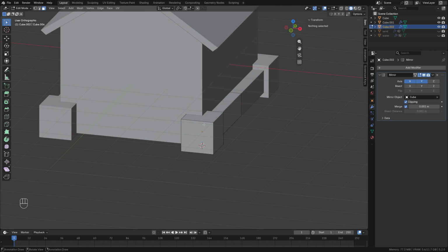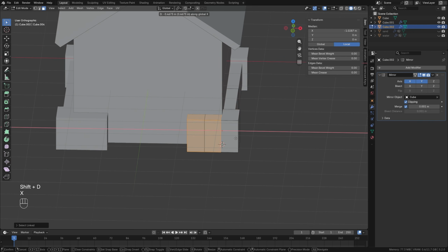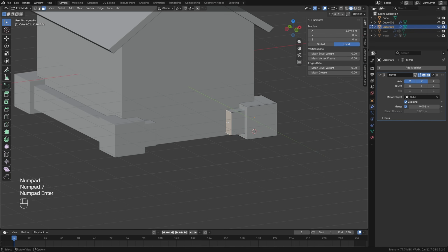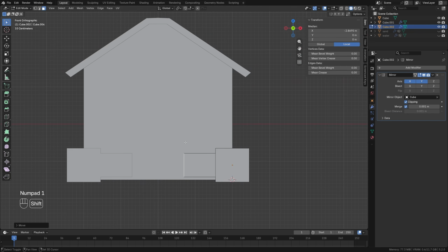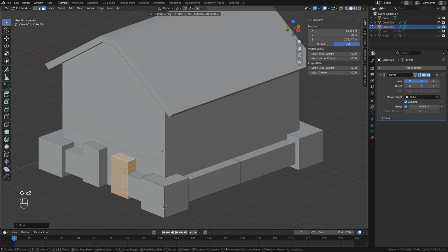Again, with the L key, we select the entire cube. In face selection mode, this works maximally conveniently. We duplicate already along the X-axis. Again, S 0.7, enter. And here we select this face and shift it a little along the X-axis to this side. Here in front will be our doors. With the L key, we select this part. With Shift plus D, we duplicate, rotate by 90, position for now in this place, extend along the Y-axis. The upper part we will raise, again for now by eye.